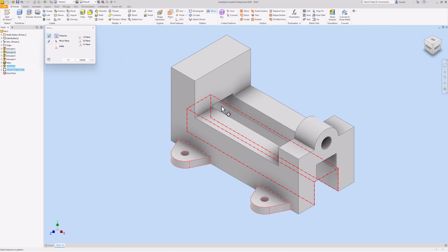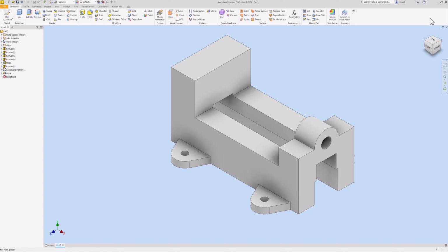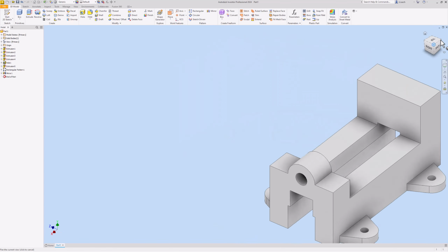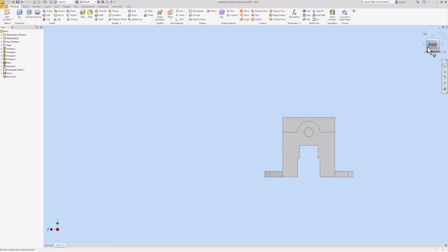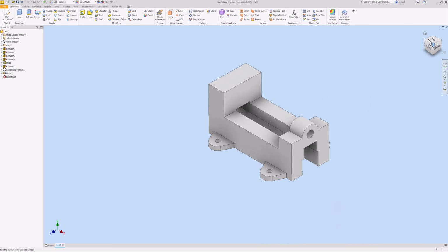So that's why when I created this, I extruded it symmetrically in both directions, so I can use my XY plane here. Mirror plane, XY, my feature, there it is, hit OK. So there, we mirrored that on the other side, nice and pretty like.